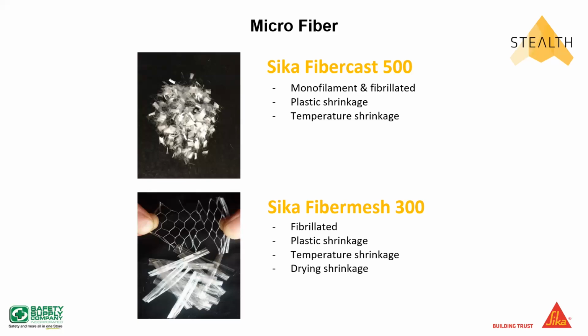That's what they're talking about when you hear fibrillating fiber. Most of your micro fibers that are fibrillating, that's what they look like when you pull them apart. Now, when you hear of a fibrillating macro fiber, we'll talk more about this shortly, but I'll tell you this note: you don't get this same action with that netting. You get more of a fraying, and the ends start to tear apart. Again, it's all about surface area that the paste within the concrete has to bond to, but the fibrillating macros don't fibrillate like the fibrillating micros.